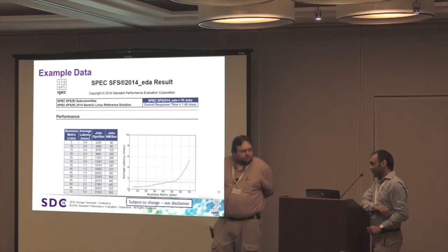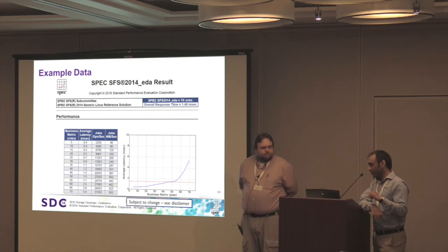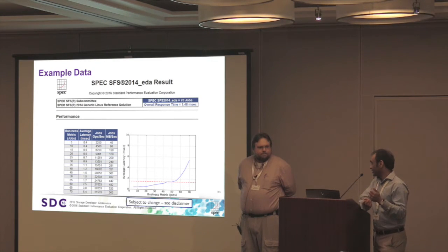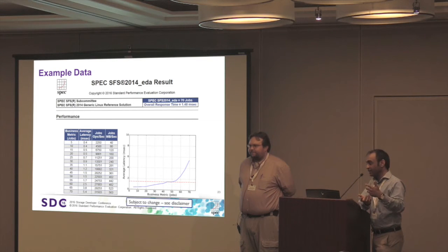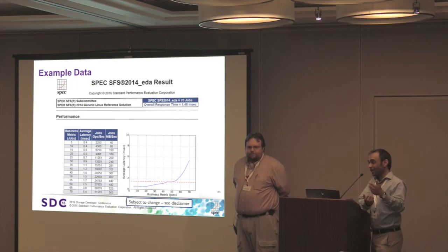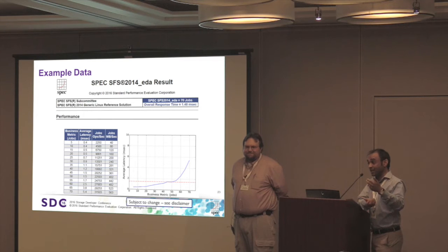So I'll also put a little bit of a customer side spin on it, or an EDA end user consumption spin on it. I actually used to model the EDA workload using SFS 2008, and that gave me exactly what Brian's talking about in terms of not having the client-side caching effect. And I presented that to many EDA customers, and they actually argued against that, saying that, well, no, I do want my client-side caching behavior to be factored in as I try to judge the performance of a storage system, because that helps me determine how I would size it.